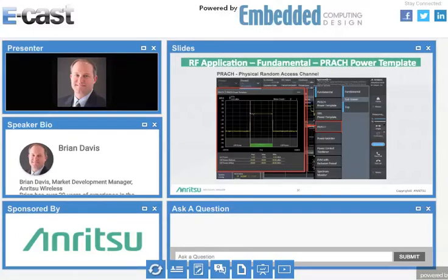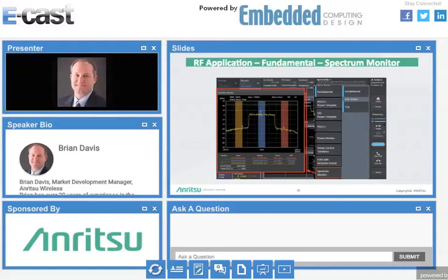And then physical random access channel. This is your PRACH. So when you need to do network acquisition, this is a measurement to say how much power you're putting out, because you're going to ramp over time. If you don't get any ACK back from the base station, you're going to keep ramping your power up. So you don't want this power to be too explosive and interfere with other users in the cell. So PRACH, that's a pretty important measurement too when you're looking at IoT devices.